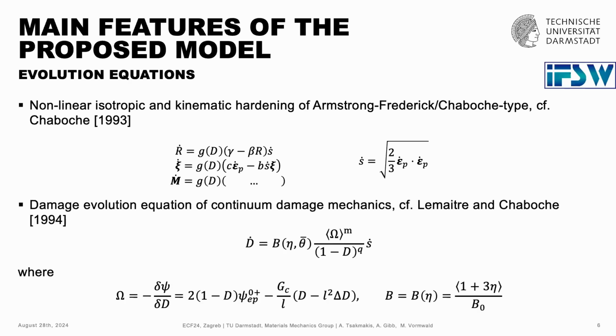As I said, we will also need a continuum damage mechanical approach. And essentially, the commonly used damage evolution equation in this case looks as follows: damage evolution is always coupled to the evolution of plastic deformation in terms of this rate here. And also, we have a so-called thermodynamical driving force, omega, which is basically very standard in the phase field approach in this manner here. Note that this here is the Laplace operator, so this omega is again a non-local quantity.